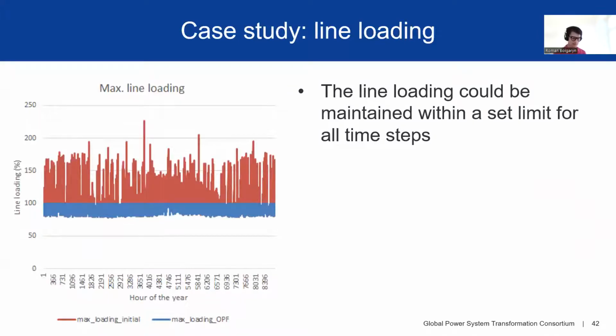We see that after performing the time series simulation for 1 year, we could achieve that all lines are not overloaded anymore. And in comparison to the red line, which was the initial simulation, you can see that the blue line maintains line loading below 100%. Next slide, please.